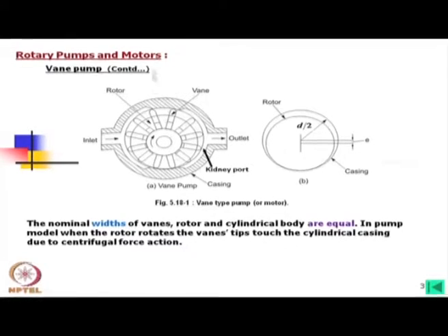Now, how is the valve arrangement? Definitely, if we consider a vertical axis, on one side there will be suction, on the other side there will be delivery. If we consider this direction of rotation, then gradually this volume is increasing. So, oil is coming in. Now, at that zone there will be the entrapped volume momentarily, not connected to any of these ports, and the next moment it will be connected to the delivery port and oil will be delivered with the pressure, and pressure is experienced by the load.